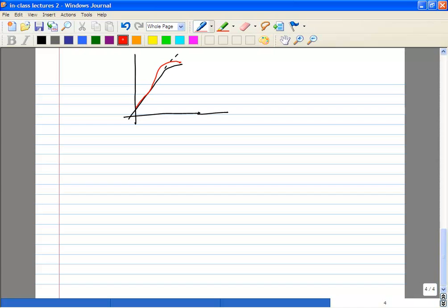Now, one of the ways you would get gain expansion is by making alpha 3 positive. What that also means is you may be adding other nonlinearities that make things worse as far as maybe the IIP3 or something else is concerned. Even though your 1 dB compression point may look slightly better, and your IIP3 may also look slightly better, there may be other harmonics which look much worse. Now the other thing you can do is try to do something like this.